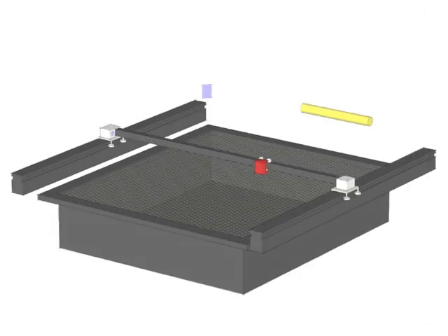Before we start using AutoCAD to set up our file, let's first cover the basic components to the laser cutter machine. The laser cutter moves along the rails on the x-axis and y-axis directions. The laser tube, shown in yellow, shoots a laser out that reflects down the left y-axis rail to a mirror, then down the x-axis rail through a lens to burn the material. The material being cut is placed on top of the laser cutter bed, which consists of a honeycomb grill to circulate air and collect fallen pieces. Beware, once pieces have fallen through, they are considered lost.